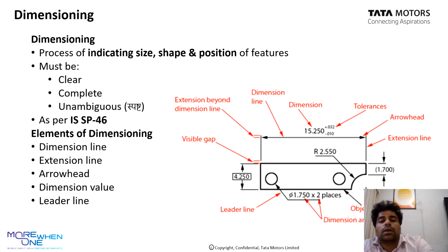Next sheet, here we can see basically how dimensions are denoted in an engineering drawing. Let's assume this is a sheet cut over here. Now, this sheet that is cut over here, you can see the dimensions of that sheet shown just beside the sheet. Here you can see there is a dimension shown. This is the way you denote a dimension, with arrows on both sides.